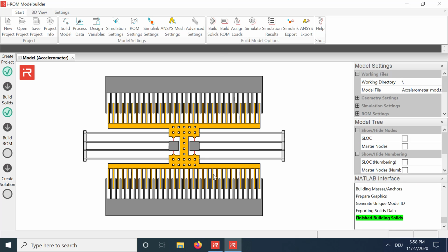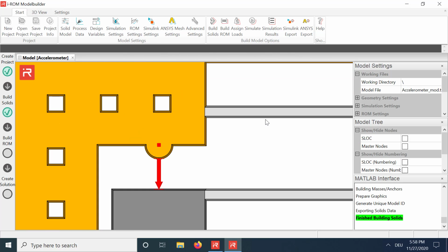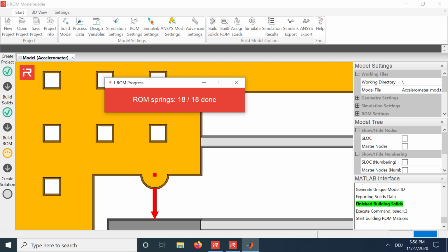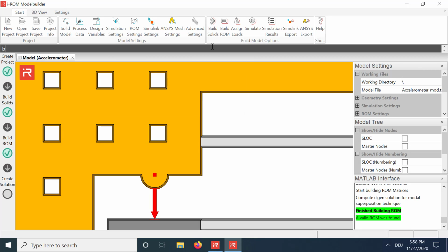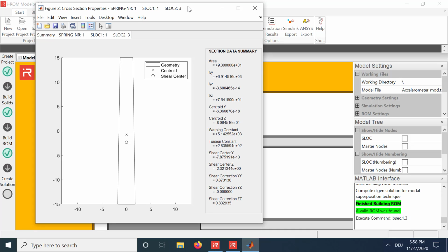Positive values make the silicon structures smaller, negative values make the silicon structures wider. The mask undercut affects all the top faces, and the offset data for the sidewall etch affect the bottom edges in the specified directions. A spring with a nominal width of 3 micrometer becomes a trapezoidal cross-section, with a width of 2.6 micrometer at the top, and 3.6 micrometer at the bottom.